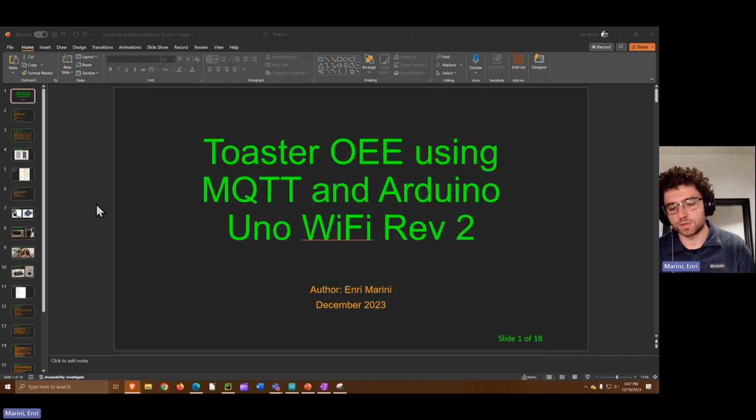In today's example, we're going to cover an implementation of tracking OEE using an Arduino Uno Wi-Fi microcontroller, hooked up to a toaster that is sensing the current via a split current transformer, and it's streaming the current values as flat MQTT, and the visualization is actually done over Streamlit. So with that, let's break down some of the things we're going to cover today.